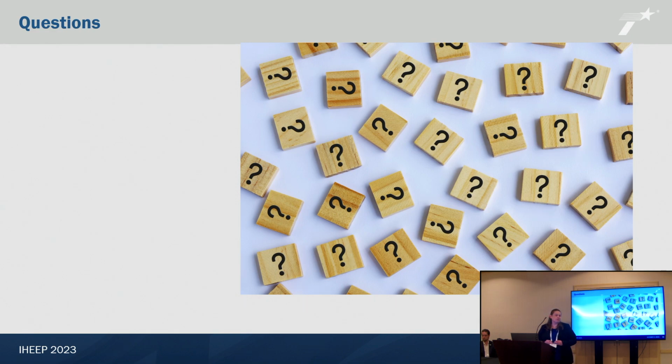Does it help to have an existing conditions model in that base survey, even if the surveyors don't know what rebar is in the existing substructure or how deep the foundations are, but if they can model a simplified OBM model in their survey base, is that helpful for the designers? So for me, it would be helpful to know where the bridge is. As far as what reinforcing is in it and how deep the foundation, that should be in the as-built, and that should be in our MBI database.